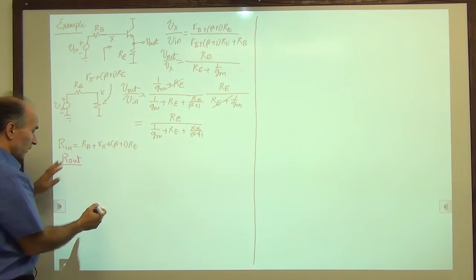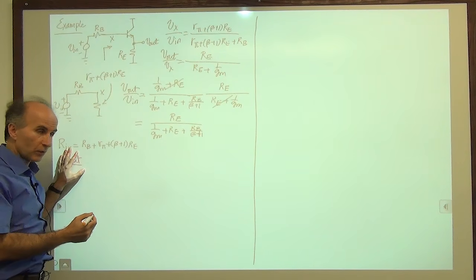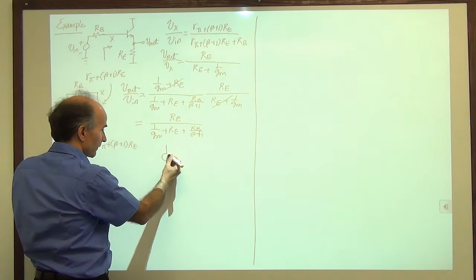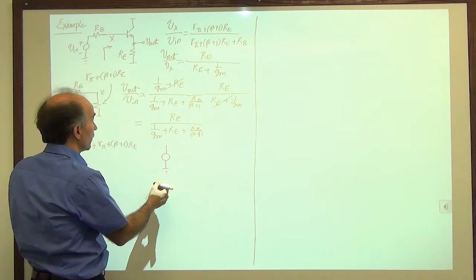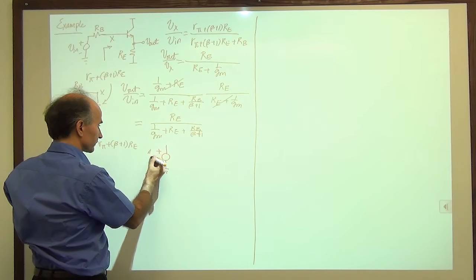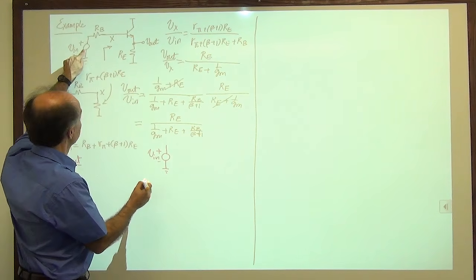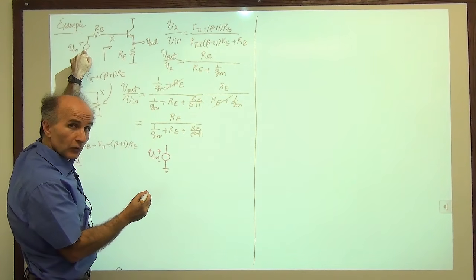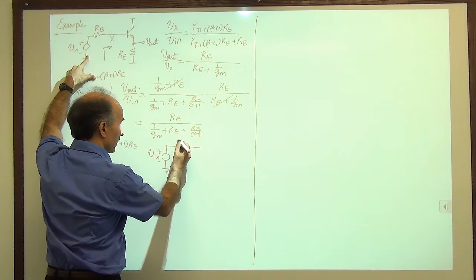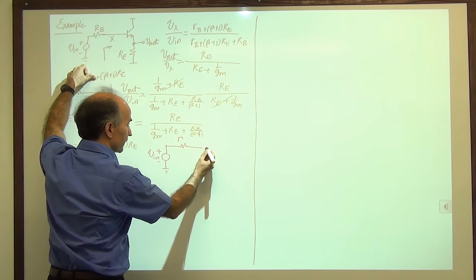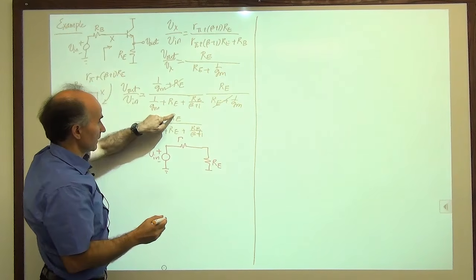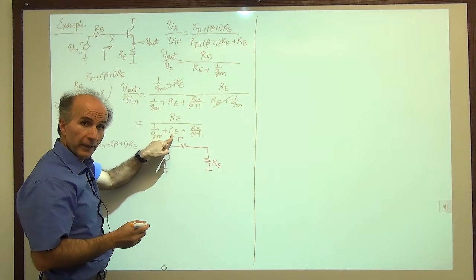This is what we have. So we're not at R out yet. We're just manipulating this, right? So if I'm manipulating this, I'm saying that what the circuit does, this whole circuit, is it takes the input, this input, and it subjects it to a resistive attenuation, where we have RE here, because it appears in both the numerator and the denominator.